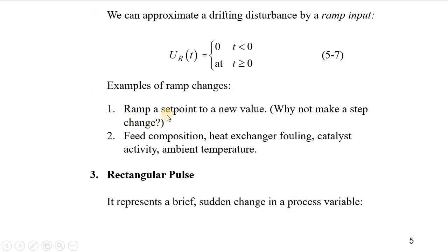And for the ramp input, again, we said that you're going from one position to another, and we have already given this previously. The ramp input tells you that it was 0, in the sense of deviation format. So there's no change, and suddenly there was a change. However, it was in a ramp manner, and we call this a ramp, a t, in the time domain, and of course this would be a over s squared in the s domain.